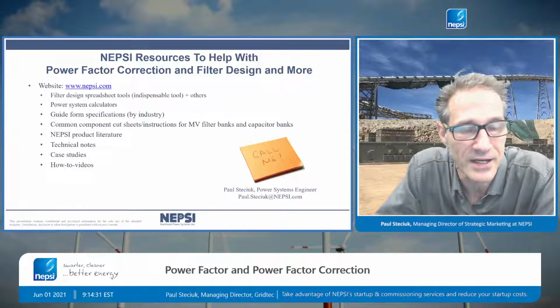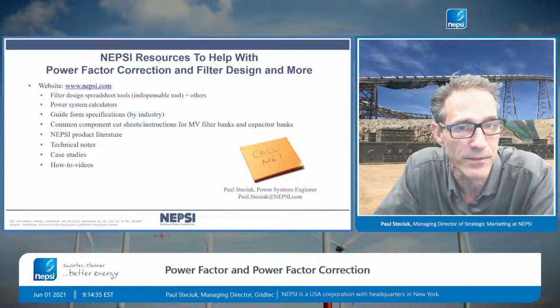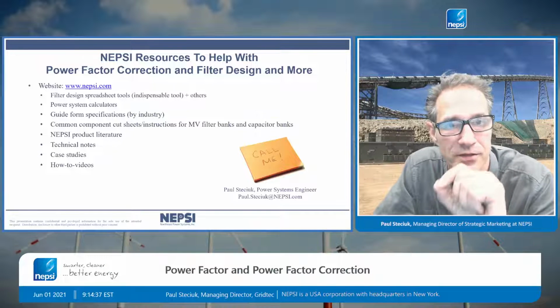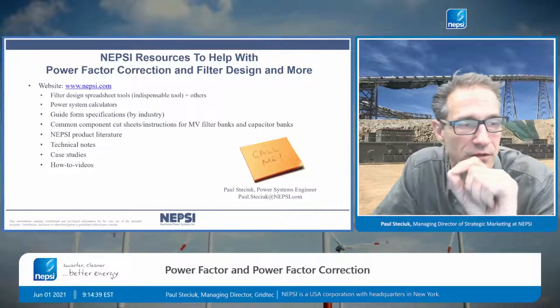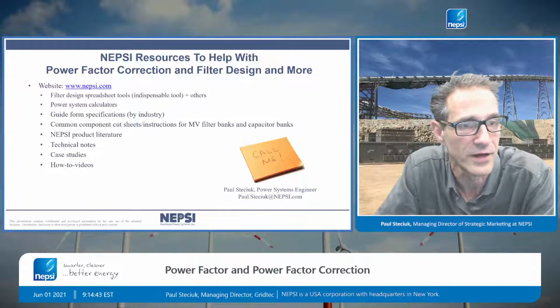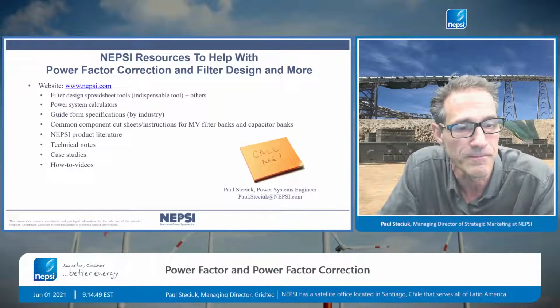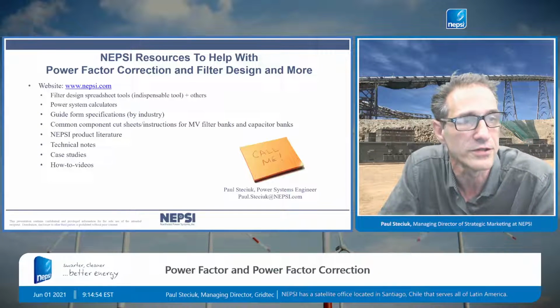They build StatCom systems, which is a power electronic version of a capacitor bank. It supplies instantaneous reactive power to the network in less than one cycle of time. So it can really mitigate voltage sags associated with motor starting and provide dynamic voltage support to the system during fault conditions.